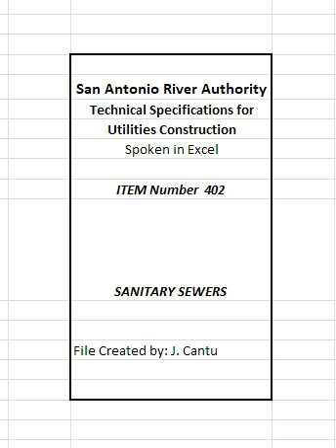402.5 Measurement. Sanitary sewers construction will be measured from center of manhole to center of manhole to determine the actual horizontal distance. 402.6 Payment. Sanitary sewers will be paid for at the contract bid price per linear foot complete in place for the size of line constructed.